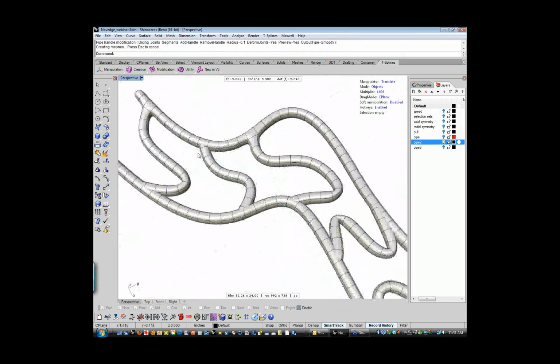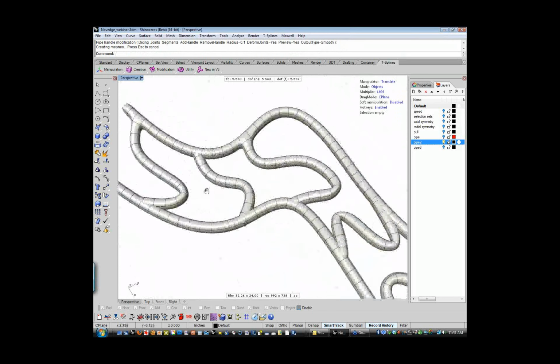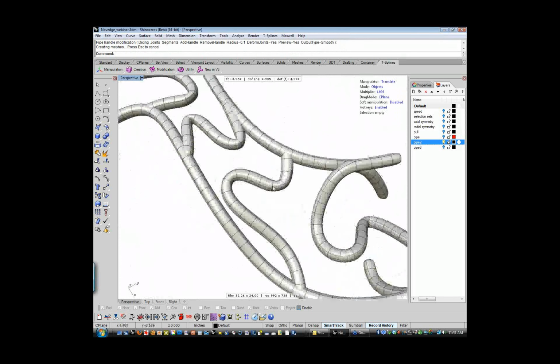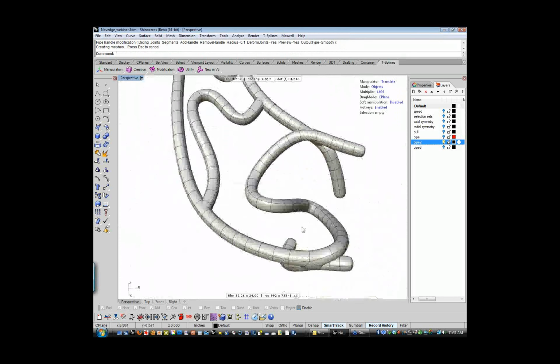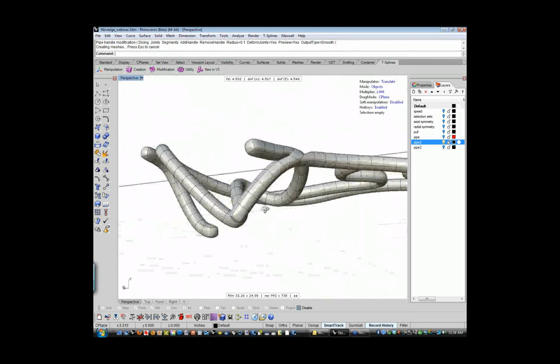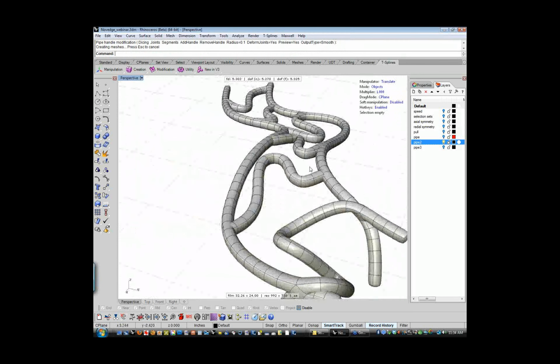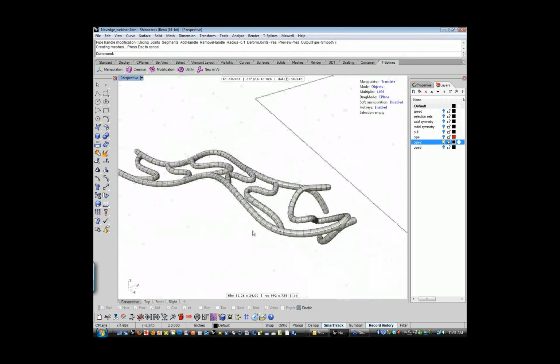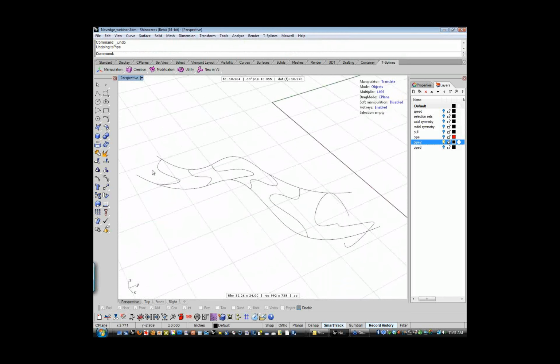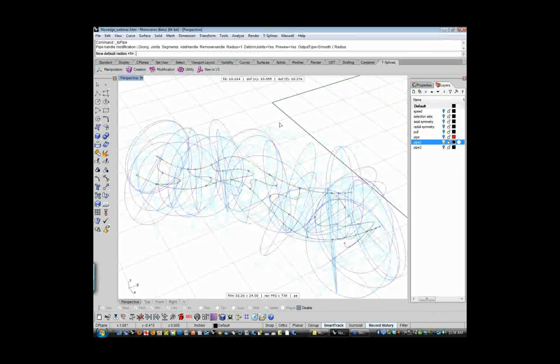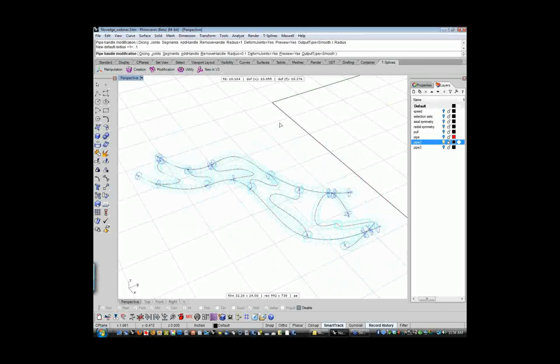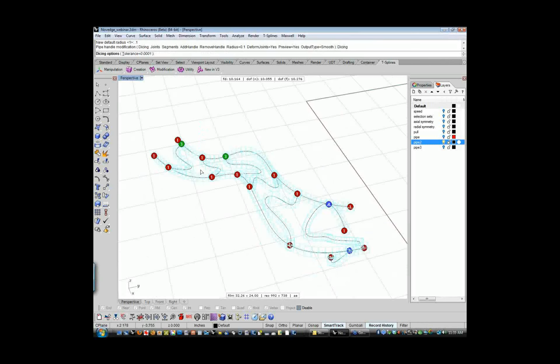And you'll notice that in most cases, it joined things up right here. Well, the reason that it didn't join up all the way, it made this intersection really nice, it made this intersection really nice, but it missed here and here and here and here. Well, there's a reason for that. It's because these curves are really sloppy, and they're not perfectly coincident where they touch. The tool actually has some stuff built in to deal with that. If I change this to 0.1 again, and then I look at the dicing, you'll notice that it'll indicate where the intersections are.